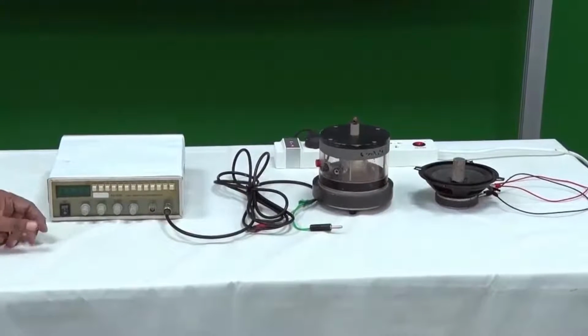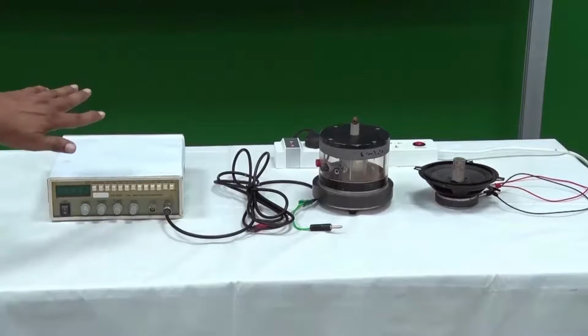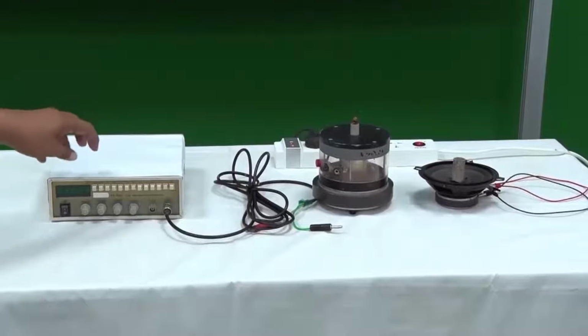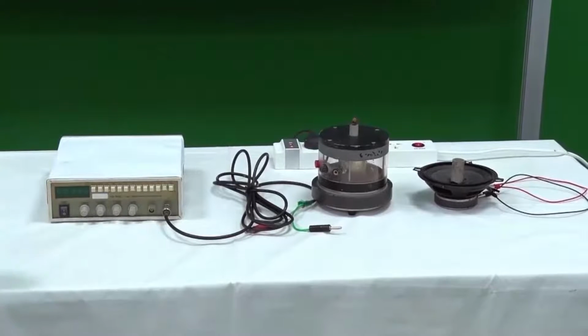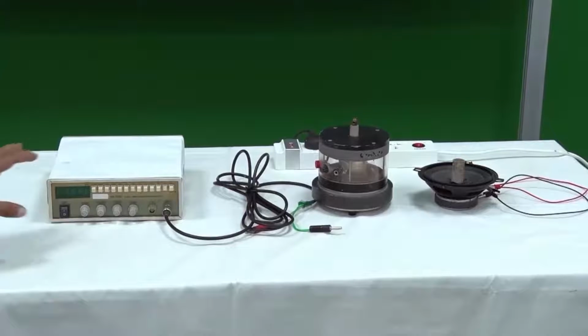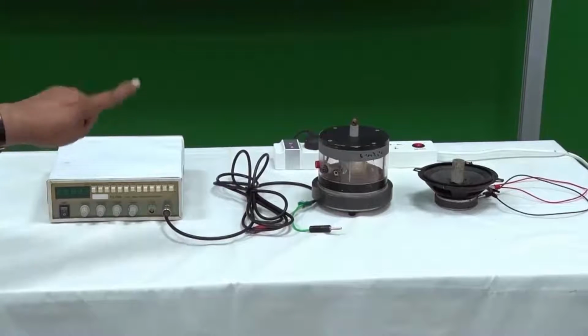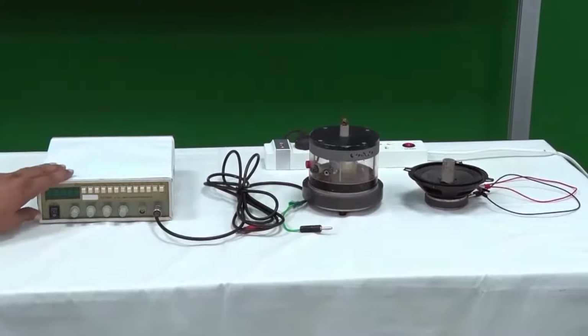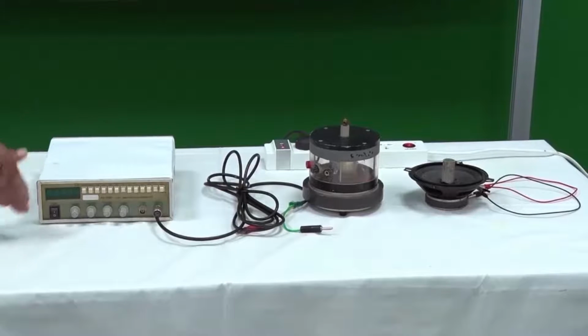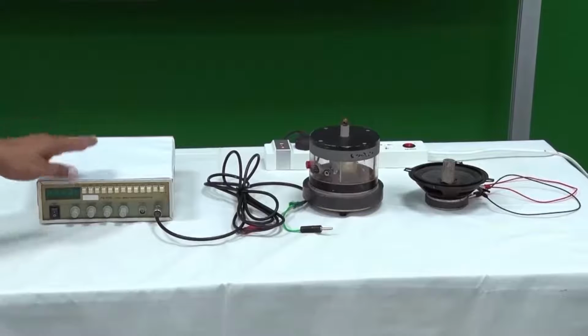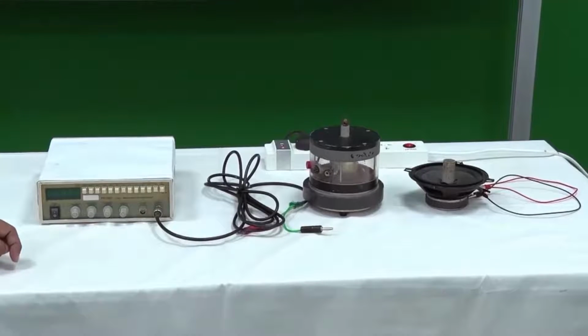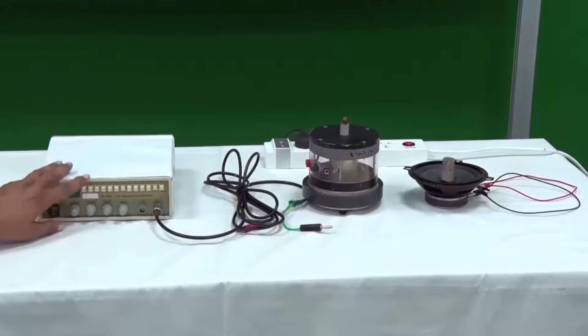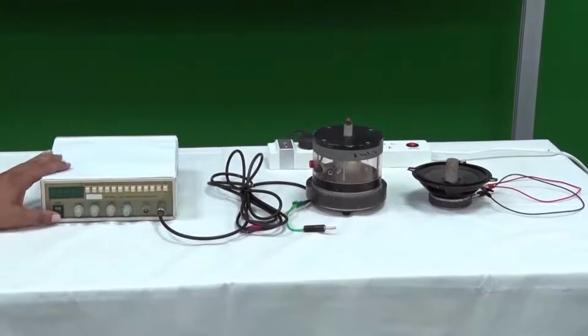So, we need DC voltages, but still we are using that 220 volt and 50 hertz power. That is because we do all our DC conversions in this unit itself, otherwise we will have to carry batteries. So it operates on AC, but it is not using that AC, because that AC is 50 hertz only. It is producing its own AC at a very different frequency, derived from the DC voltages which are converted from that AC from the power supply, and that DC is actually used for this oscillator circuit.